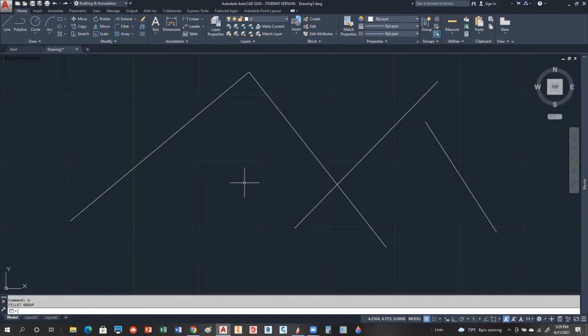It says fillet radius is too large. Oh, well, that's what's wrong. Okay, it can't fit the fillet in based on what your vertex is. You don't have enough room. So what you can do is try setting your fillet radius to, what did you use, 1, did you say? Yeah. Try setting it down to like 0.25, just to see if that works.